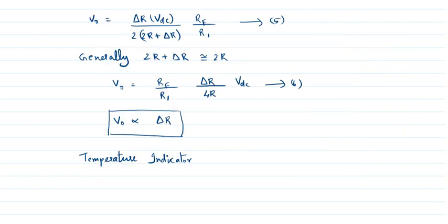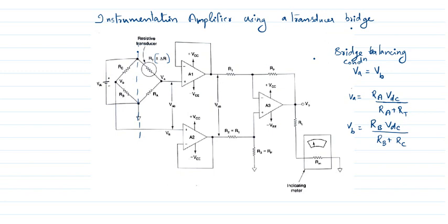The second application will be the light intensity meter. In this case, instead of a thermistor, we use photocells. So we generally use a photocell as the light intensity meter. The bridge can be balanced for the darkness condition. Therefore, when exposed to light, what will happen? The bridge will become unbalanced and cause the meter to deflect according to the resistance.